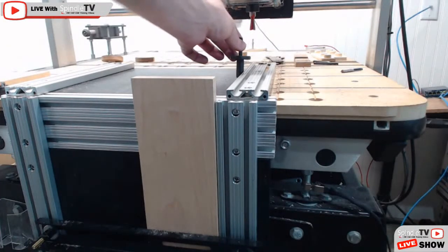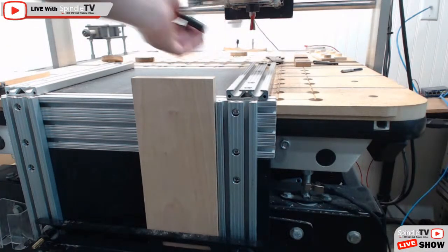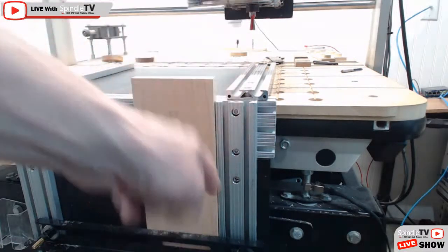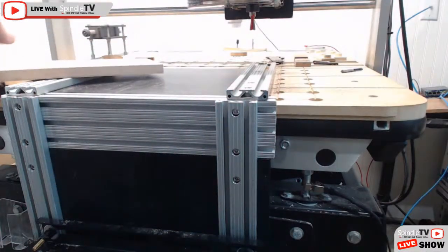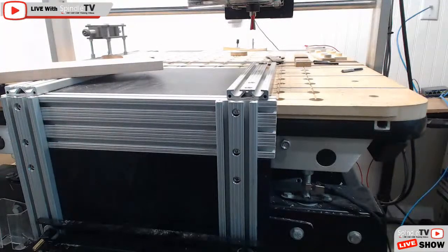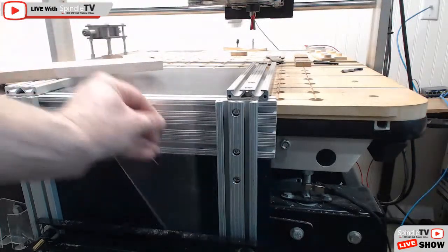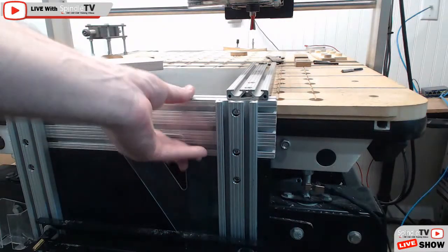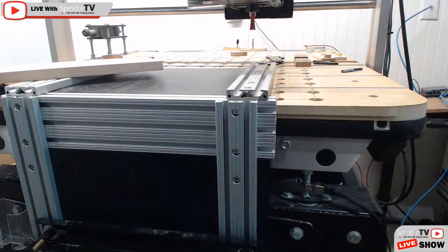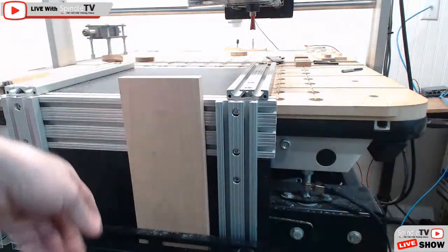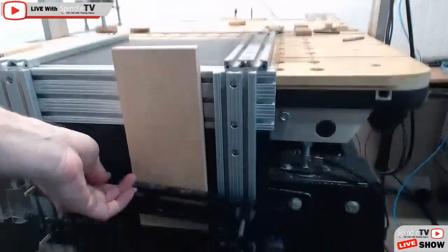I put it in my router and I run it along my fence to make sure that my fence is running true to the CNC machine. And then from there, I adjust this fence and make sure that it is square. Oops, it would help if I turn it around. Make sure that it is square to the top part of that jig, which I am, and everything. So it's all about the setup and making sure that everything gets right. Now, I happen to have this lower fence down here.